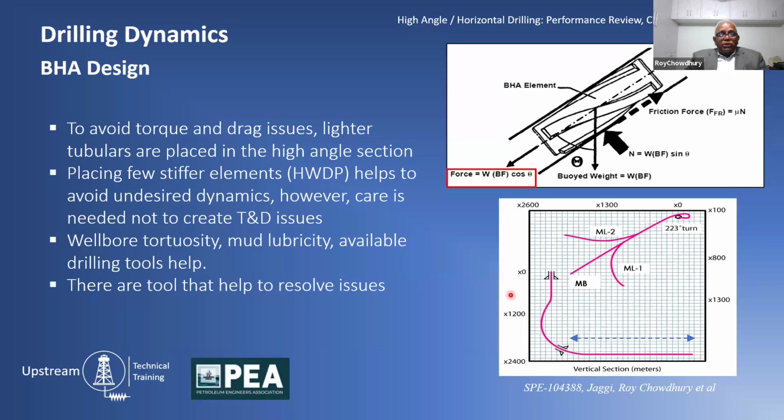as well as it withstands the lateral vibration also. Now, I'm sure many drilling professionals know that as you increase the inclination, the component of weight on bit that acts on the bottom is the cosine of the inclination. So at some point you lose, it is like a diminishing return.